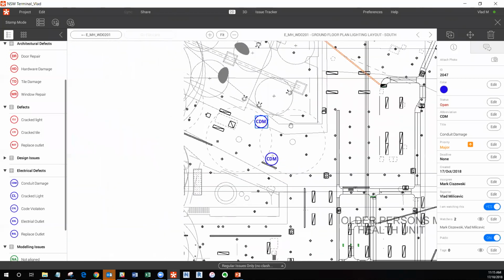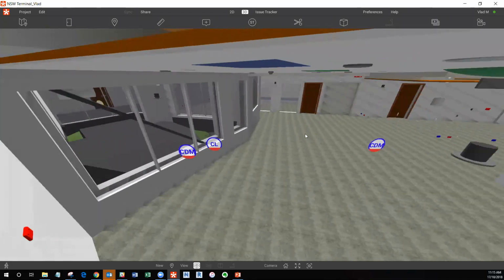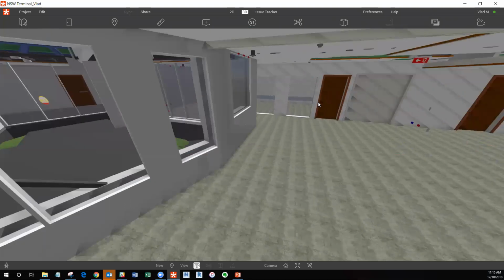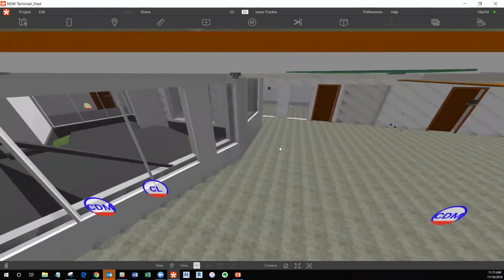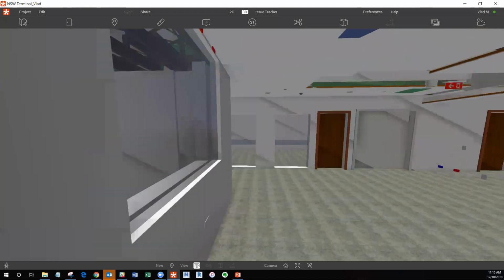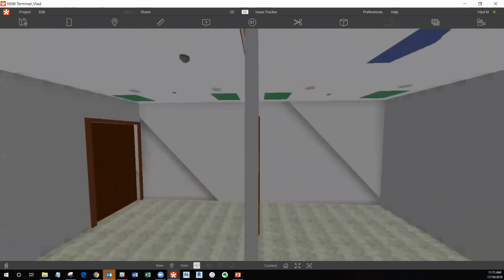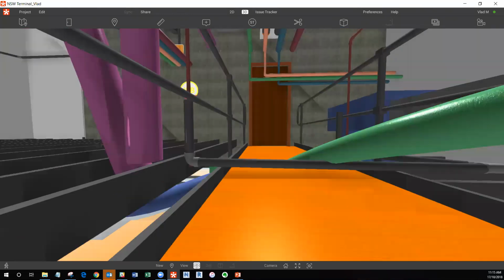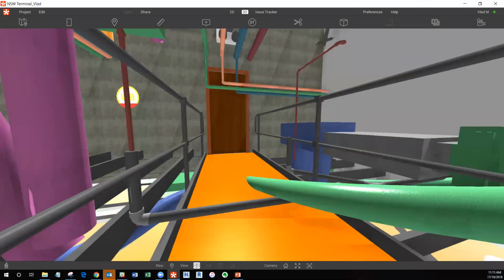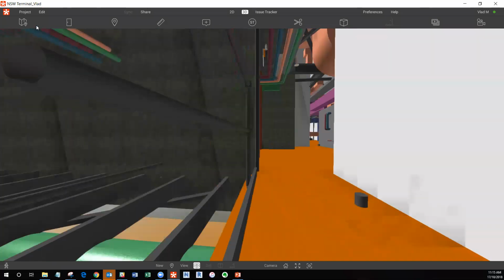Now, that's pretty much how you do that in the 2D mode, and an additional value is that I'll just click on those now. I've got back into my 3D mode, and anything that's just stamped in 2D will be transferred to the 3D mode as well, but you can also do direct stamping from 3D, and that's especially useful if you're doing design coordination, for example, and you want to walk around and stamp something, especially something that's possibly repetitive.